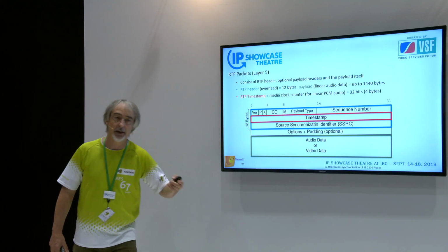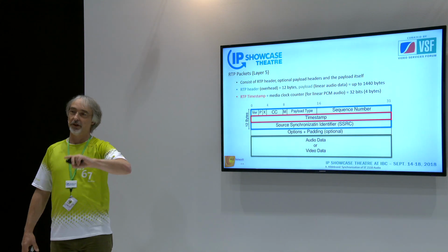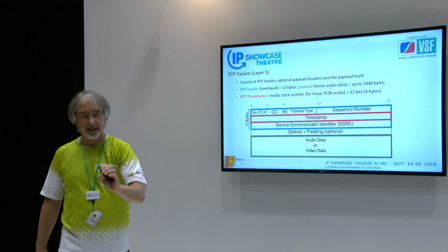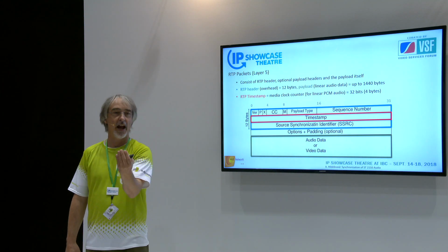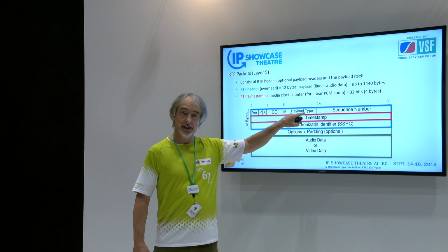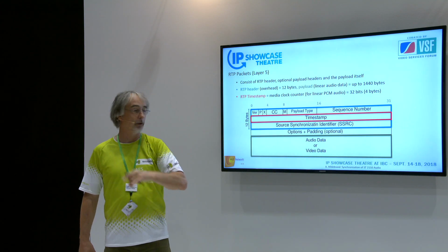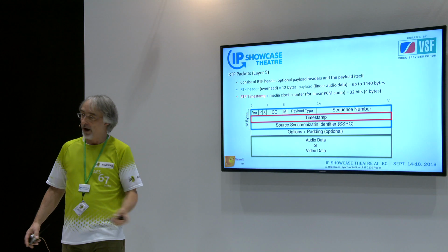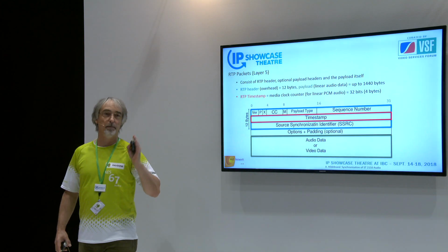And there's some math behind it, but the math is not very complicated and should allow the receiver to exactly identify, okay, I'm receiving that packet, the first sample. When has that been generated, wherever it had been generated? Because it's written here as the media clock counter, referring to the system clock, to the overall clock time of the day. So now we know, for every individual sample, when it has accurately been created.